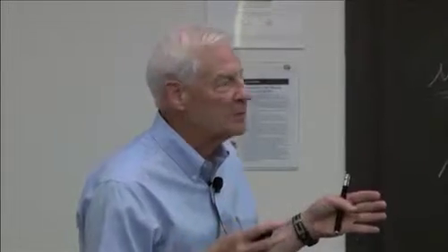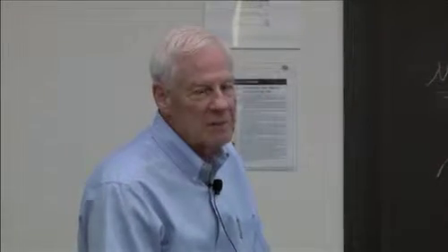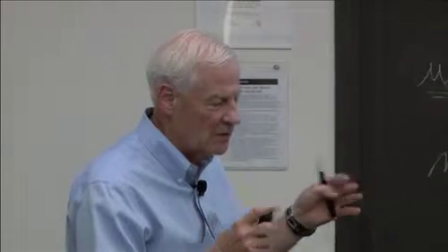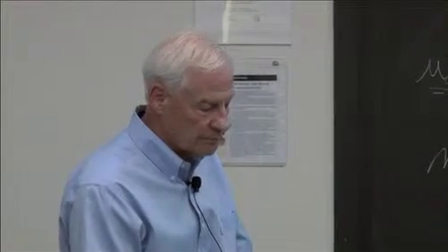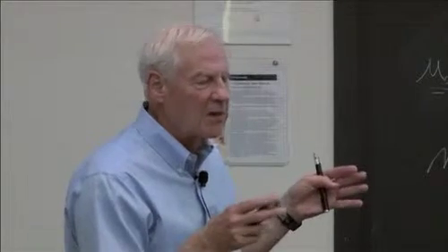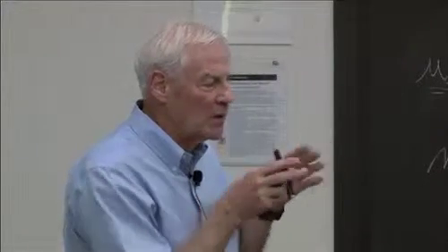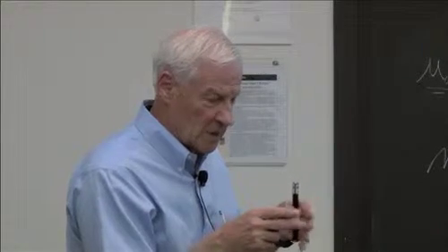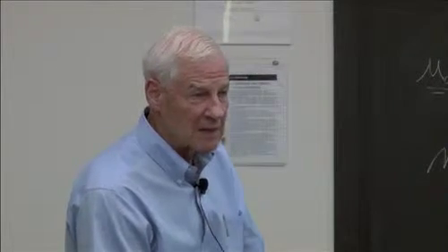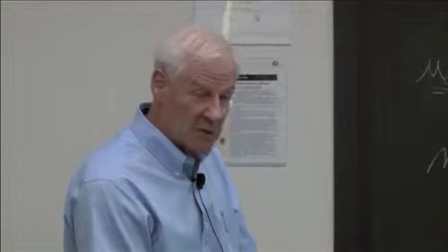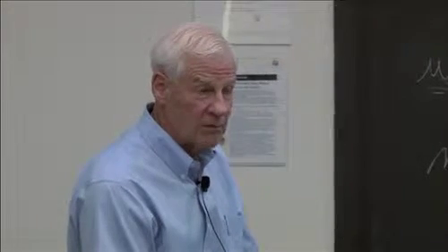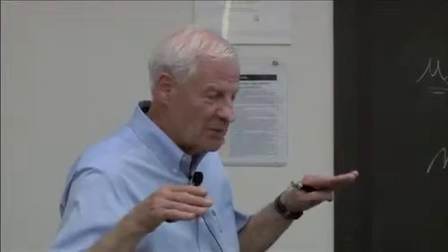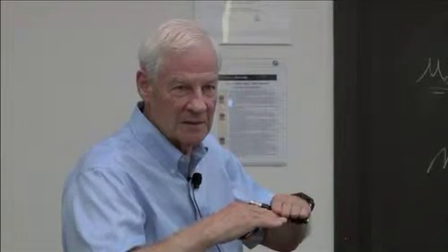We're going to spend an hour talking about shock tubes, techniques, applications, the latest versions of how you do shock tube experiments. Why? Shock tubes are a very convenient way to generate a very well-known sample of high temperature gas. And you'd like to study perhaps the chemistry that takes place in that sample by measuring the species evolution with time, for example, using laser absorption. So laser absorption and shock tubes are made for each other.